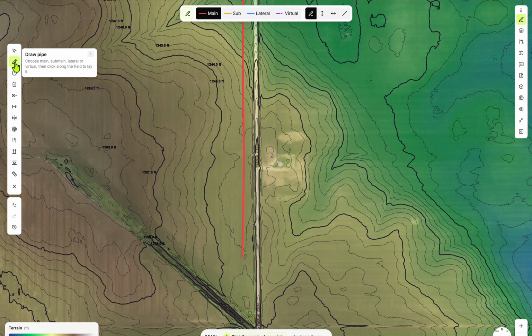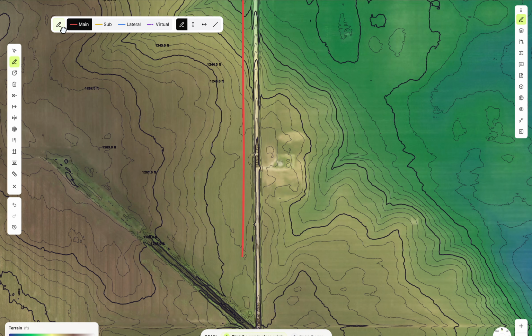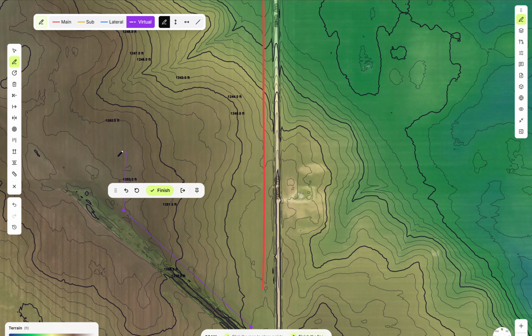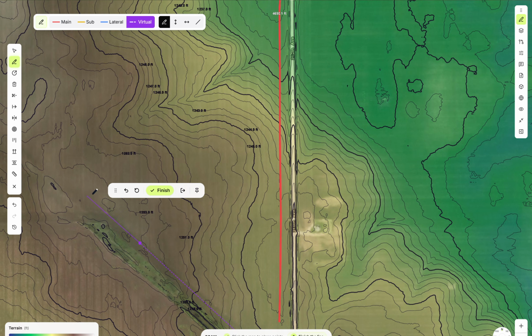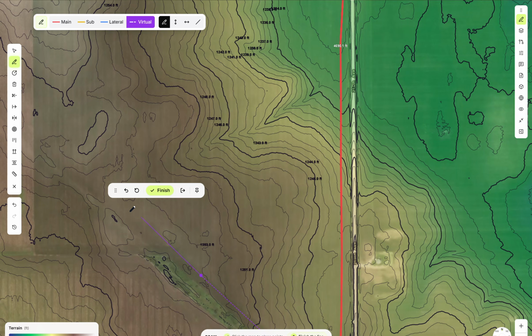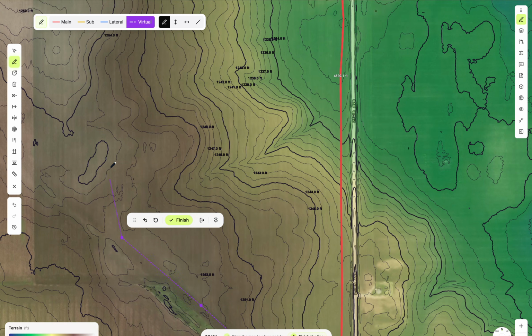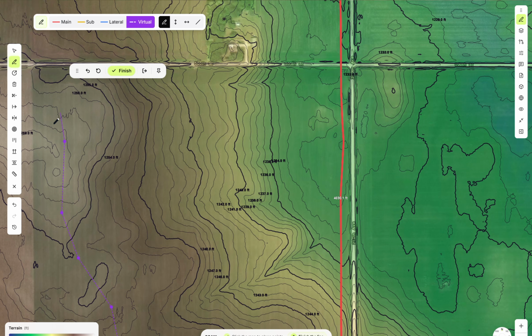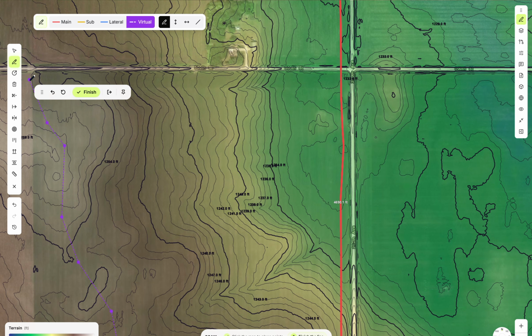At the top here, this box pops up where you can pick laterals, virtual, whatever. Then I'll throw my virtual line in. This can be used for a boundary or a place you want to extend your lines to. And when extending to these, you can have an offset. Also, what's nice about the virtual line, you can leave them in, you don't have to delete them. They don't get exported as lines, they don't show up on maps. It's only used on the design side.